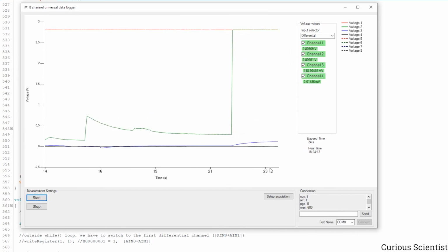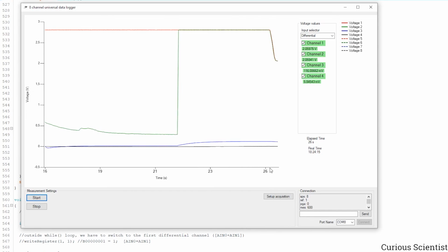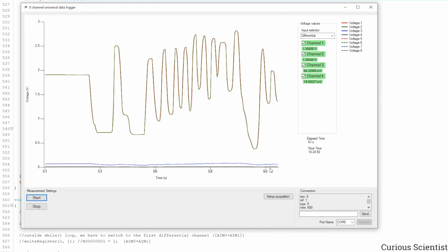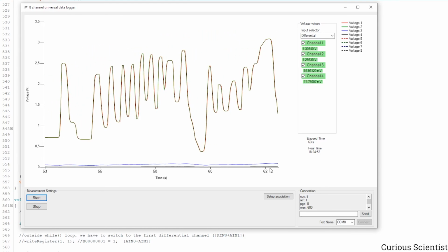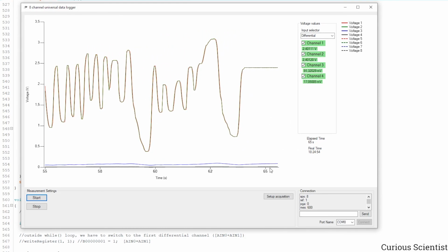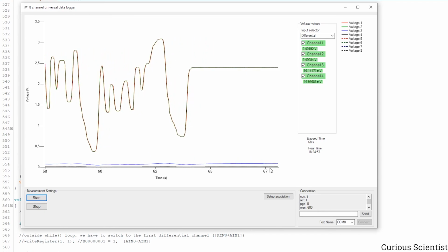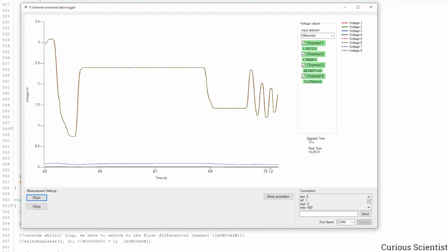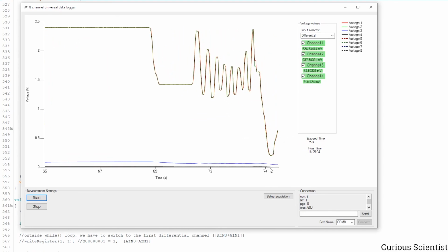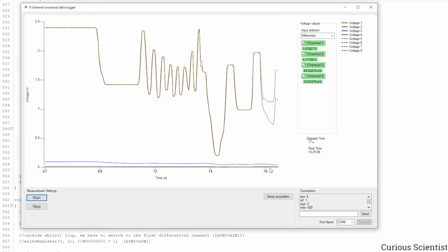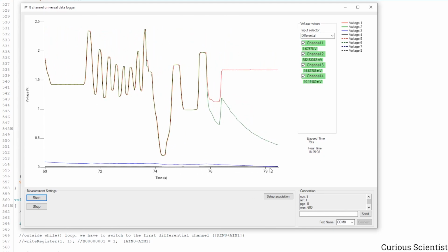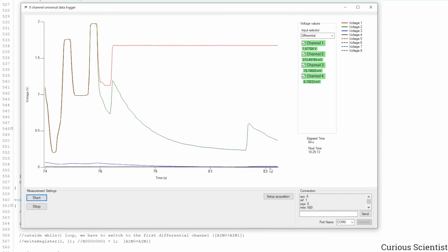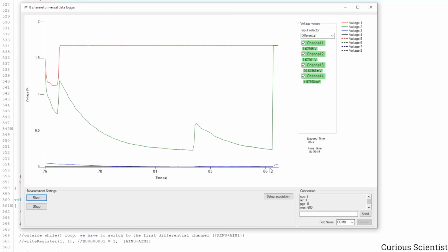There we go. So now they are connected to the same, and you can see that the red and the green are following each other very nicely. And that also proves that the cycling is a very quick process. So when you change from channel 1 to channel 2 inside the AD converter, that happens very fast. And now one cable got loose. So you can see, I don't know, that's probably the capacitor discharging. Let's put it back.